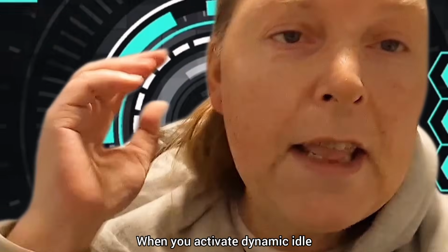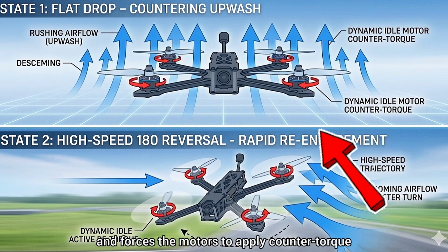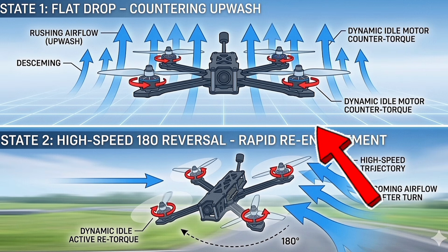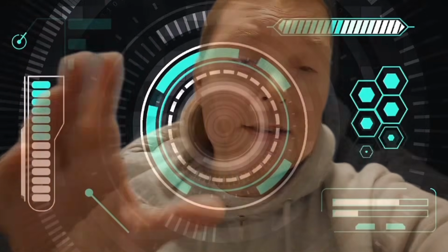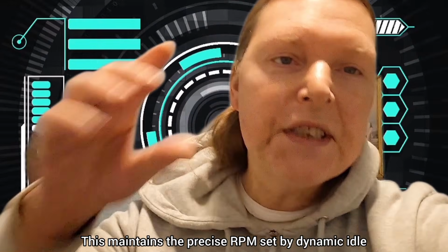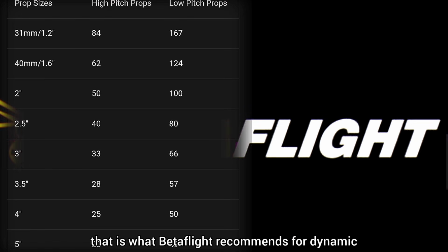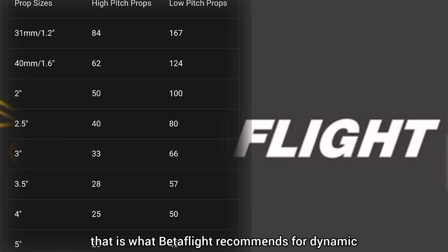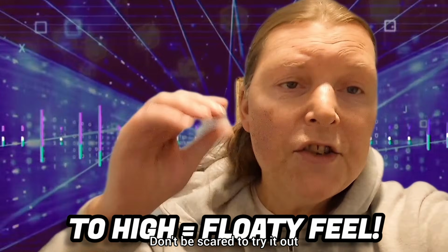When you activate dynamic idle, it detects these forces and forces the motors to apply counter torque, as shown in the illustration by the small red arrows. The motors are actively fighting the air to slow down the propellers against the oncoming rush of air. This maintains the precise RPM set by dynamic idle. And if you look at this up there, that is what Betaflight recommends for dynamic idle settings for the prop size. Don't be scared to try it out.